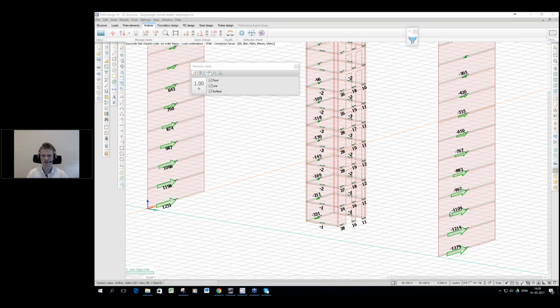I don't know about the Norwegian and the Swedish, what options you have. You can also say that in a slab span, half goes here and half goes there. It's also up to you, but that's not what the FEM does. Then you can put releases on the end of your prefab slabs to obtain that distribution as well. So it doesn't work as one long beam element that distributes load.